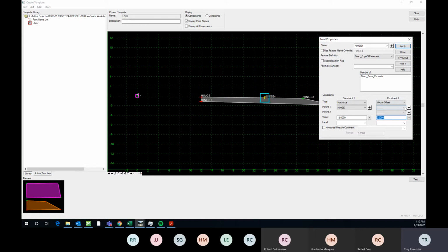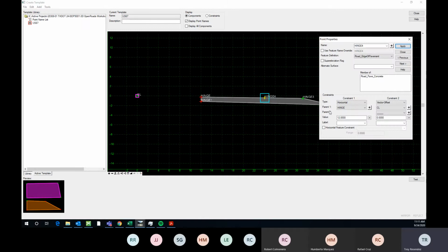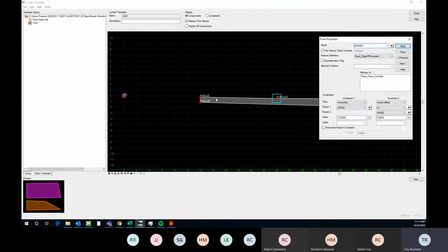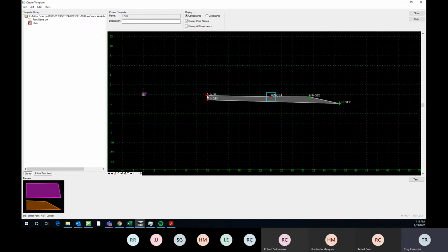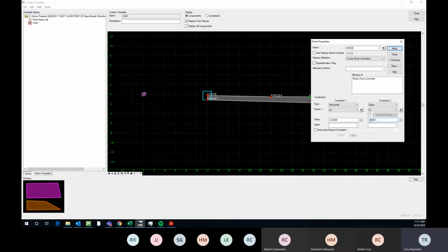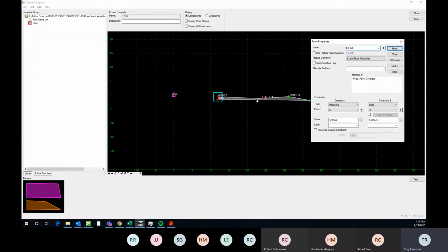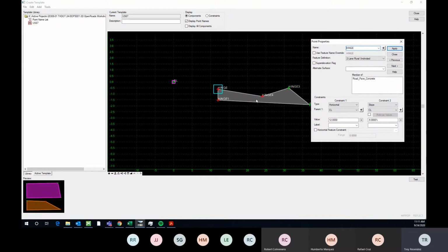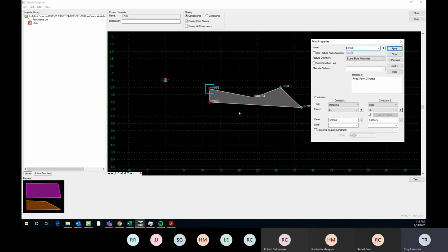So for this first parent, I'm going to click the center line, and the second is going to be this hinge, and I'm going to make sure this is 0. Now I'm going to show you what this does. If I come here to the hinge and change this slope to 5, then, and a cool tip is if you hold shift and scroll down and up, you can see it vertically exaggerated, so you can have a better feel of what's happening.